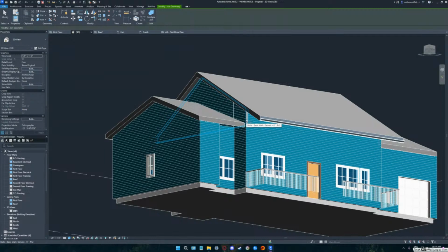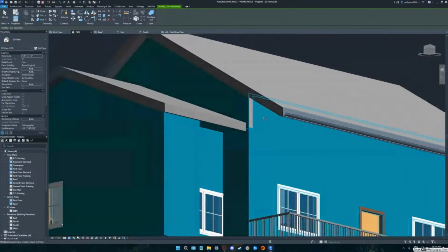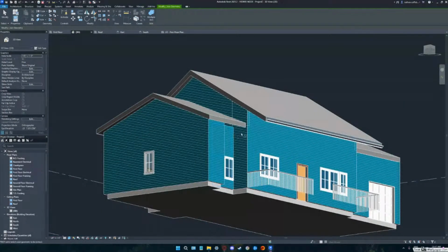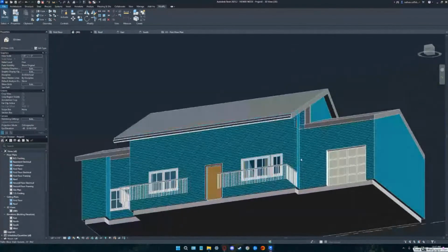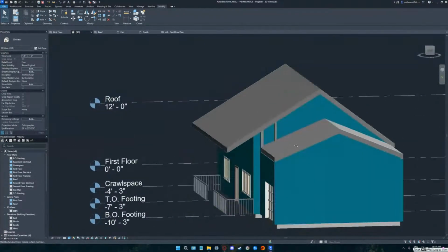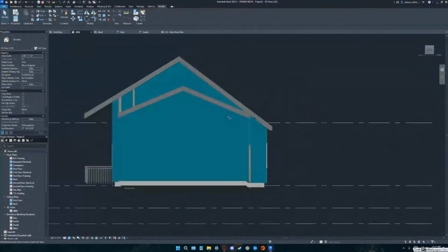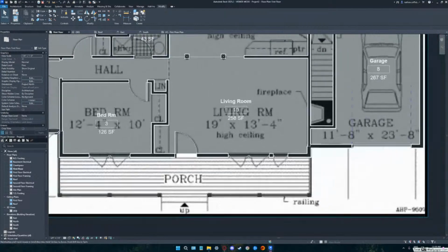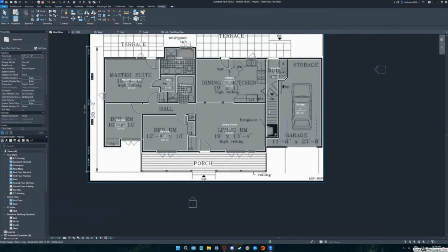And remember this. The join command was exactly like the cut command I showed you earlier. It's which one you pick first. So if it didn't work, you might hit undo and you might pick the front wall first and then the side wall second. There you go. See how that one worked and the other one didn't? Yeah. Same thing over here then. Yep. What is that? Those are your walls inside. That wasn't showing before, was it? I think it's because your one roof wall got moved just a little bit. Oh, okay.